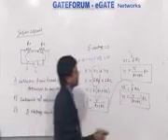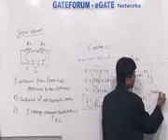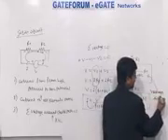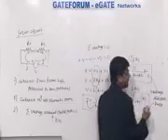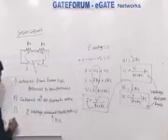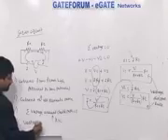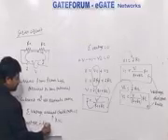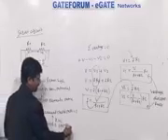Now this is called the voltage division rule. This indicates that in a series circuit, voltage is divided. So another property of a series circuit, the fourth property, I can say, is that voltage is divided and the voltage division rule is applicable.